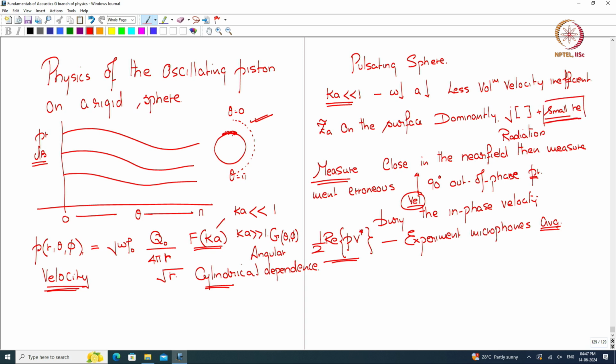But we were talking of what is the dominant behavior. How does the radiator dominantly see the remaining space in that manner, by ignoring or neglecting this, but it is there. So, now if you want to measure even the small component that is being radiated, you have to go to the far field of the small radiator.